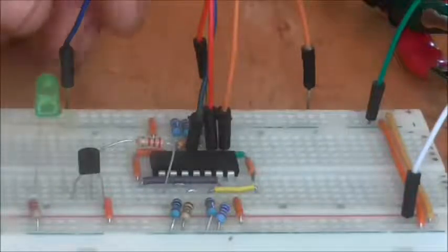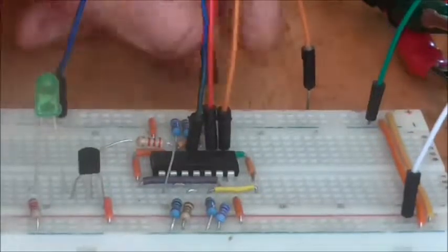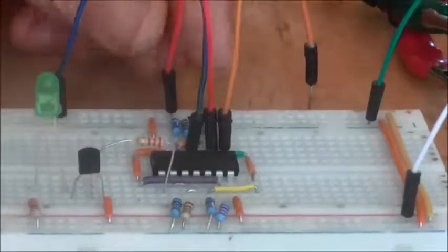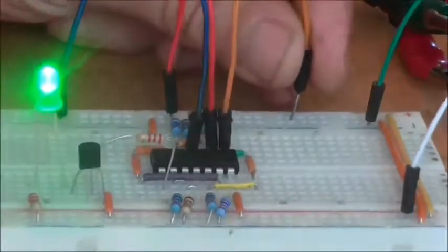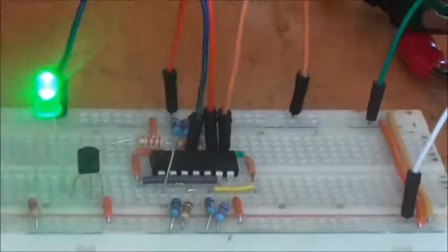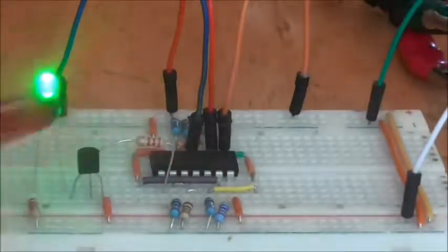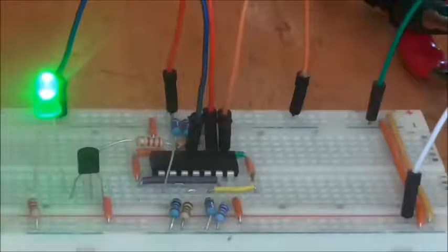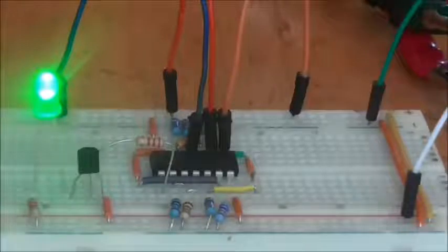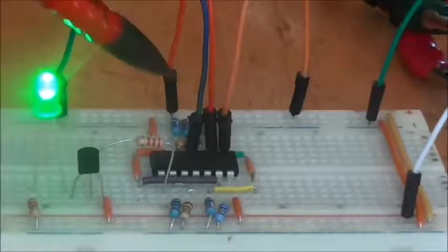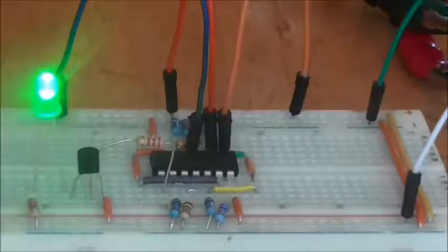Well, let's plug things in. There's input C, there's input B, and there's input A, and the LED shines nicely. So it doesn't look as though we're going to have any problems with fanning out components coming out of this last gate, and the reason for that is that this last gate is acting both as a buffer and an inverter, and so it shouldn't alter the impedance on the rest of the circuit in the gates there. Well, that's the theory. So what we'll do now is we'll get the thyristor that we couldn't use last time, and we'll put it in and see what happens.